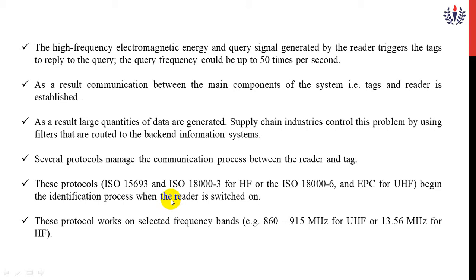Generally, in an RFID system, the protocol works on selected frequency bands. The range is 860 to 915 MHz for UHF or 13.56 MHz for high frequency.